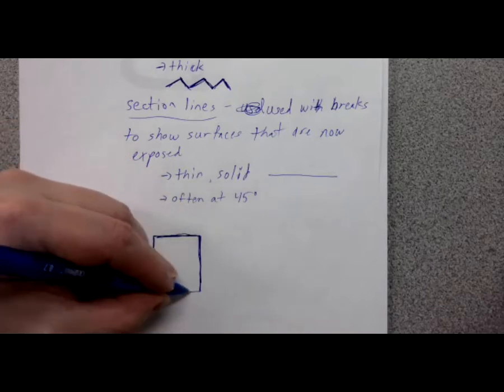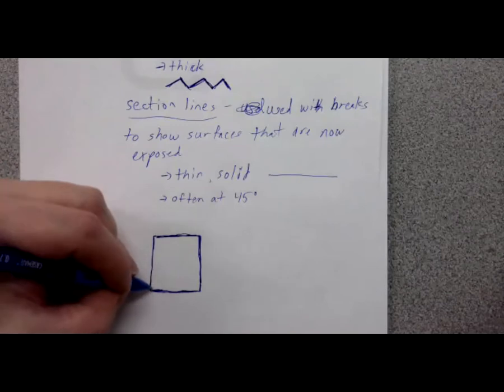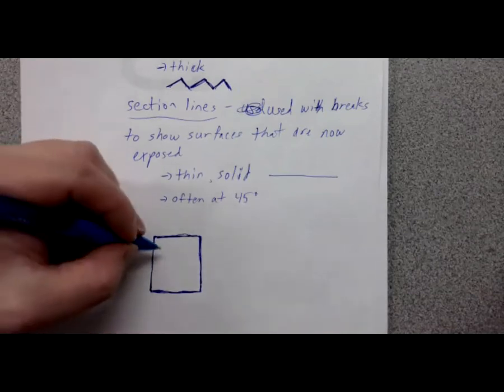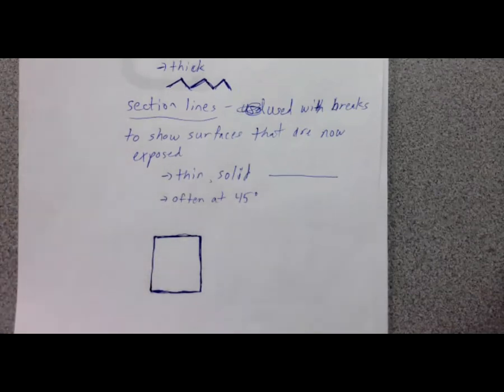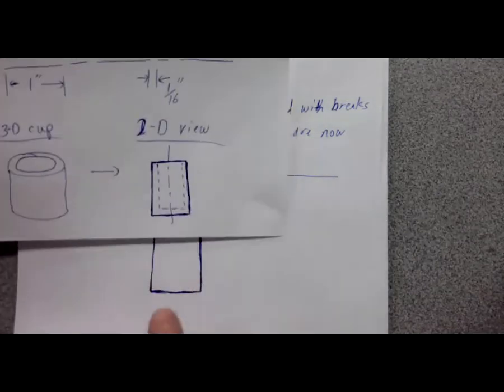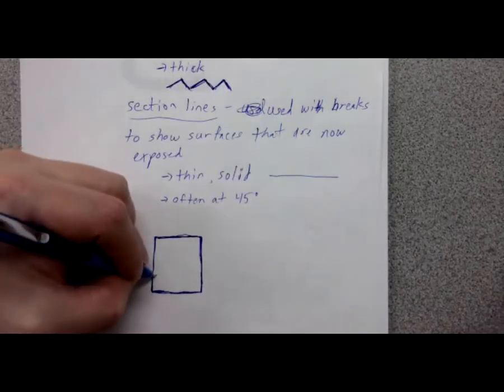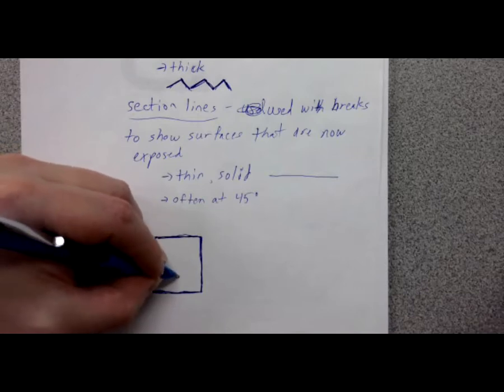And that's where I apply some kind of a break and I maybe zoom in a little bit and I can draw more detail. And so if I have this two-dimensional cup that I had earlier, and again, a cup when viewed in two dimensions from the front or the side, the outline I'm going to see is going to be this rectangle. From this view, I can't tell you what this rectangle represents. We're going to talk next time about using more than one view to represent something in multiple dimensions. But if I'm just looking at the front on view, this is all I see. And again, as earlier, you can draw your hidden lines in here, right? But before I draw the hidden lines, what I'm going to do is I'm going to say, well, let's draw a break down here on the bottom of this thing.